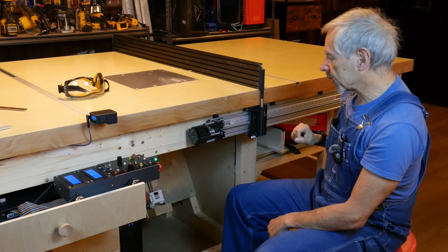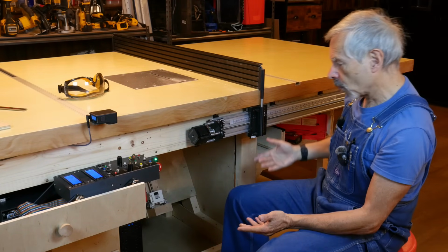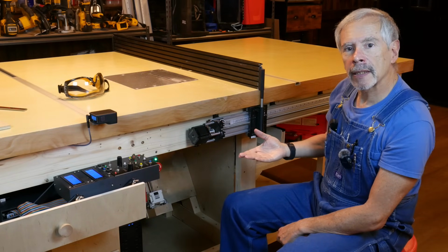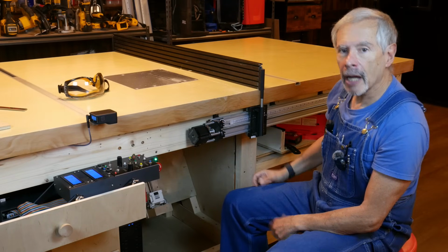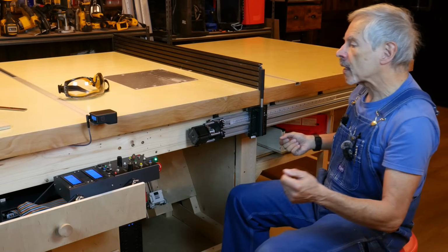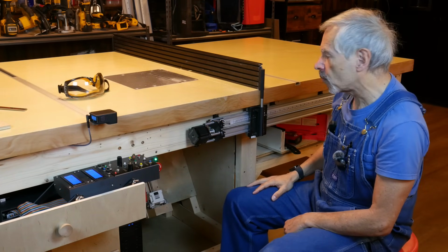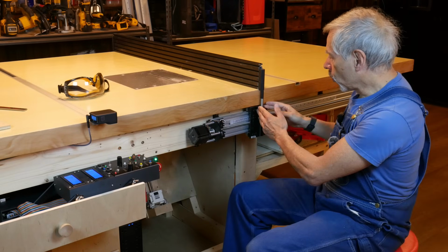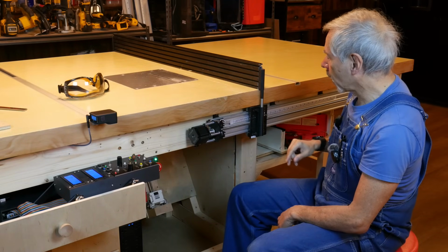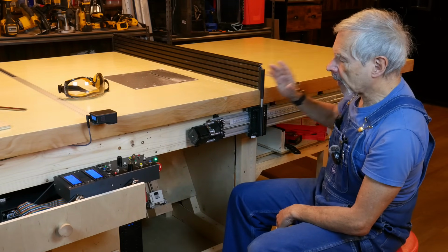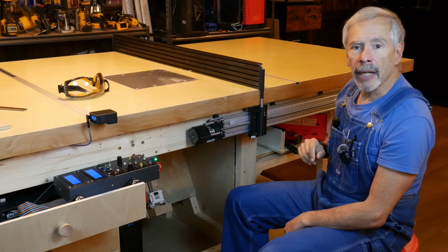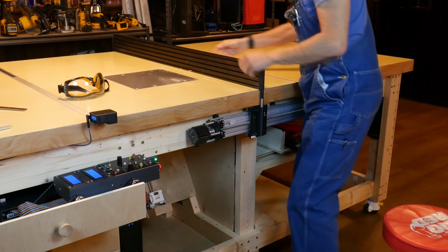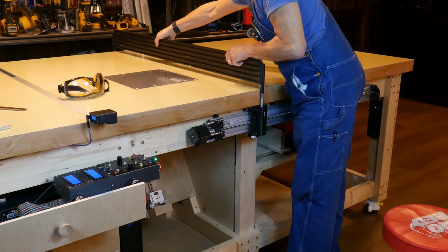So what does the stepper motor do when it can't move? It slips. That means it receives pulses but doesn't do anything. And who would? If there's a clamp in the way, the motor can't move, and so it didn't move. Now, if this fence was rigidly connected to both linear actuators, and if one motor stops while the other keeps moving, things would break. That's not good, and so in order to avoid such breakage, I designed the fence in the following manner.